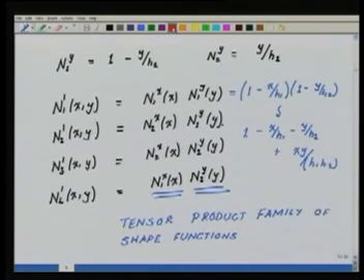So see, this part is the linear part. It is linear in x and y. This part is actually bilinear. That is, it is not linear, it is more than linear in x and y. So these shape functions seem to represent more than the set of functions we need to represent completely to define a linear. That is, they contain more terms than just the linears.